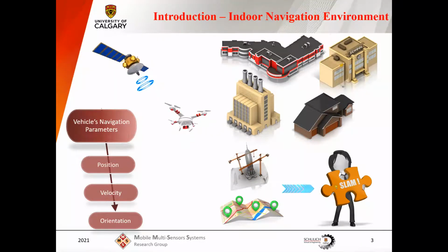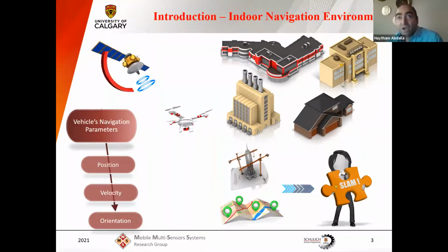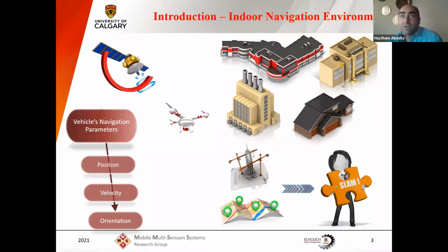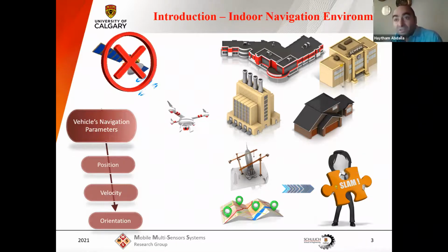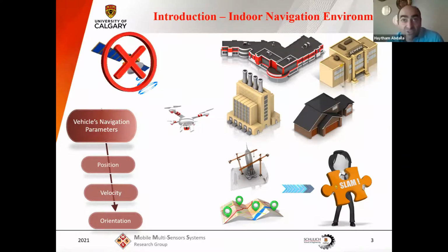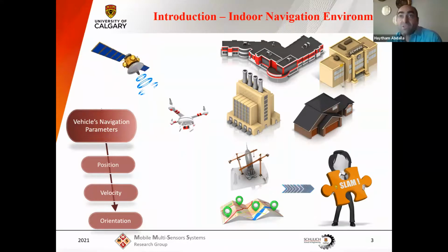Regarding the cave, we used here the IRKF algorithm, okay? And by the way, we submitted this IRKF algorithm, and it is a novel algorithm, and it has good results compared with other methods. But for the cave, we will not use the IRKF algorithm because the IRKF algorithm depends on the features. And in a cave, we can't find features. So we can use another method, for example, iterative closest point, ICP, okay? Because it depends on the points themselves. It doesn't need any features.